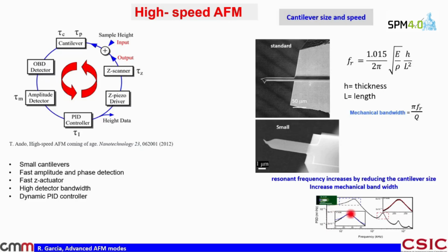So at the end, what happens intuitively? You know, this is the resonance, the first resonance. So in high-speed AFM, you have to move everything fast. But this fast motion, for the cantilever, has to be at this frequency here, far from the resonance. Why is that? Because if you excite the cantilever with a force at a frequency close to the resonance, the cantilever is going to amplify that, and that amplification is noise.